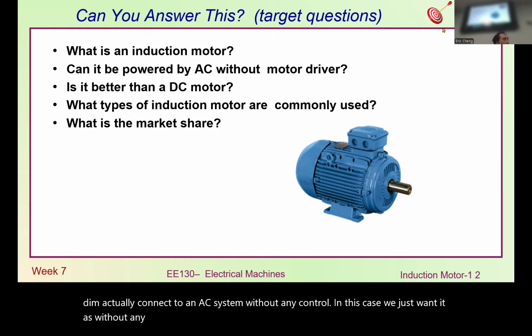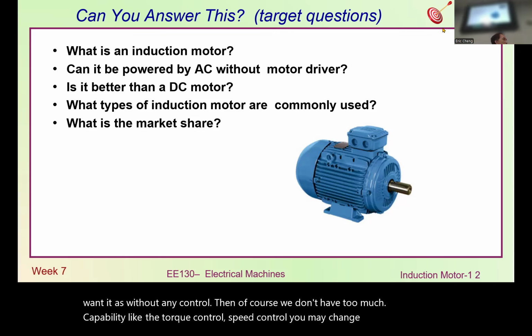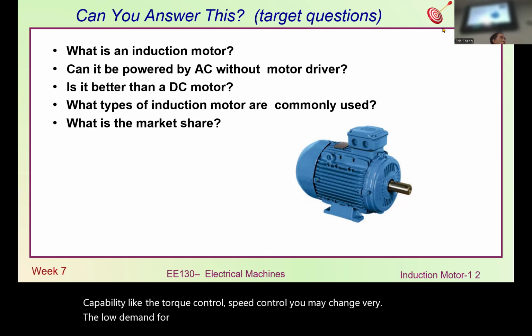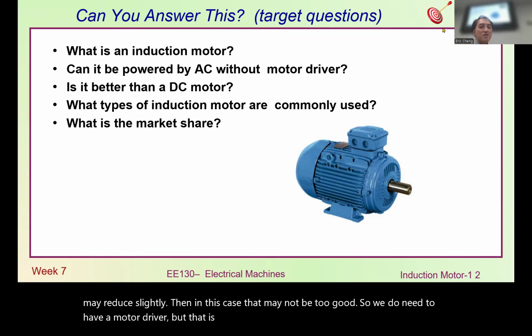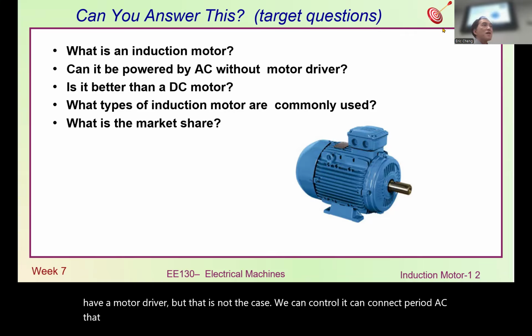Then of course we don't have much capability like torque control or speed control. The speed may vary with the load demand. For instance, when you drive the motor at heavy load, the speed may reduce slightly, and that may not be too good. So we do need a motor driver in some cases, but it is not always necessary. We can connect purely AC, and that also works. That is why the induction motor became so famous and popular.